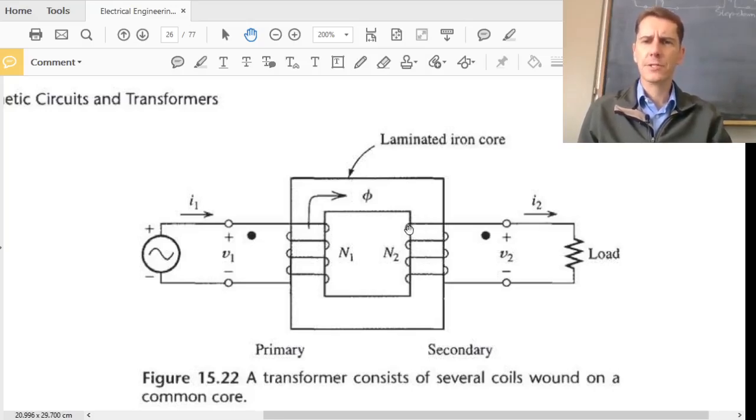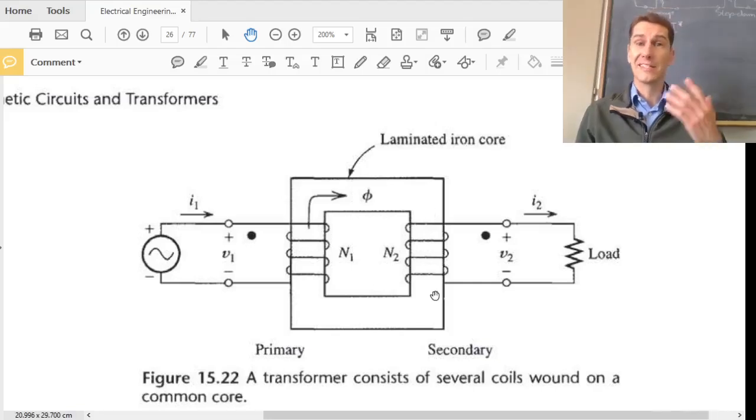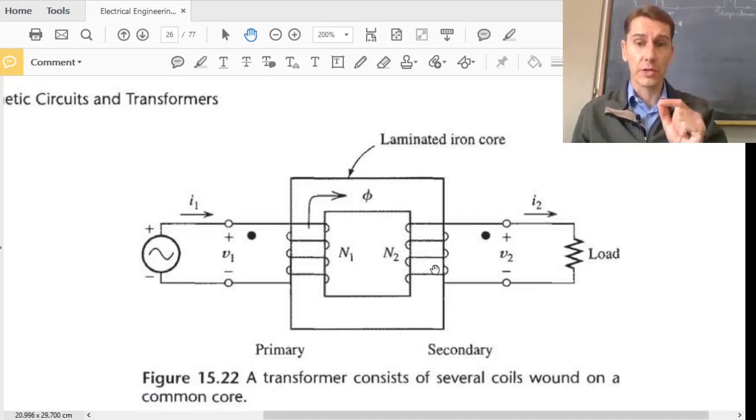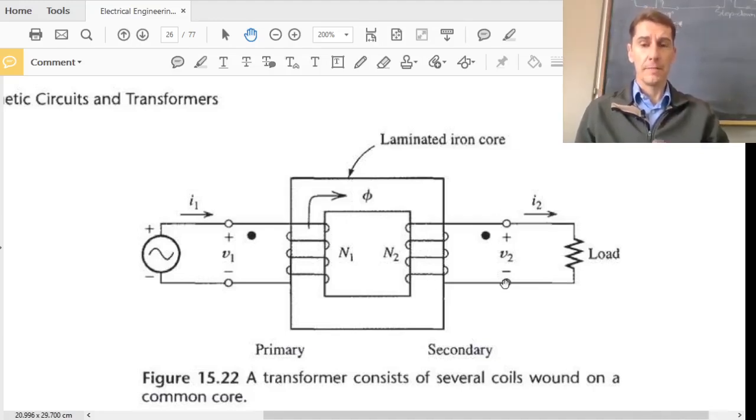All right, so that goes through that coil, and this flux links coil number 2. Now we remember mutual flux, and this is where the mutual inductance comes in. Because the flux is changing through coil 2, Faraday's law induces not a current, but a voltage across those two terminals. You will only get current flowing if you've got something connected between those two terminals. So even without the load, that voltage will still be there.